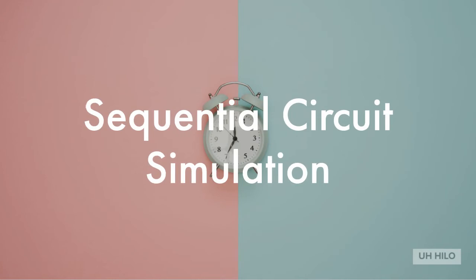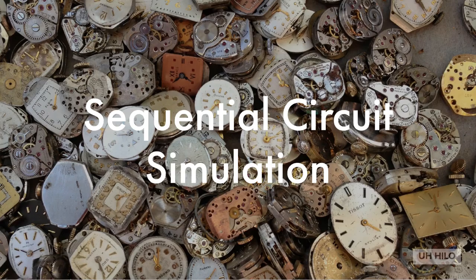Simulation of sequential circuits is different from their combinational counterparts for several reasons. First of all, rather than a set of input patterns for which the order of application is immaterial, the patterns must be applied in a sequence. Second, there must be some means to place a circuit in a known state. Realistically, initialization to a known state is accomplished by application of an initialization subsequence at the beginning of the simulation. In the simplest case, we can use the reset signal.